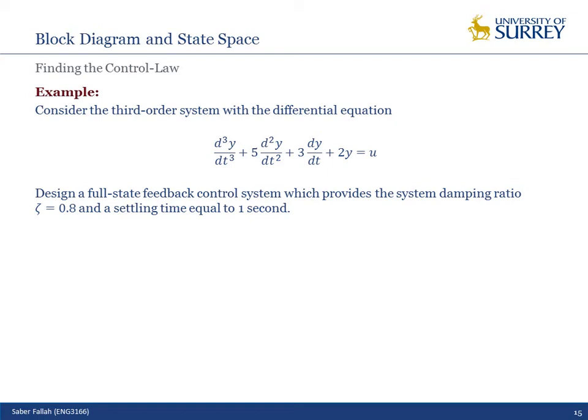What will be the characteristic equation in the state space domain? The inverse of sI minus F. Okay, for the uncontrolled system. For the control system, what's the characteristic equation? If you answer this one, you get 100%. U equals KX, and then... K times sI minus F. Correct, exactly. So you're done.